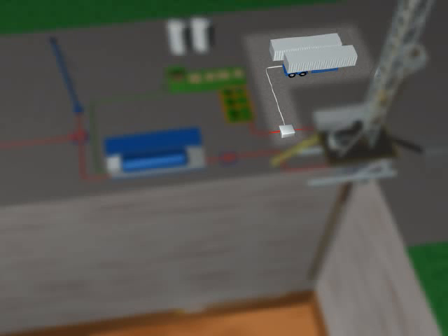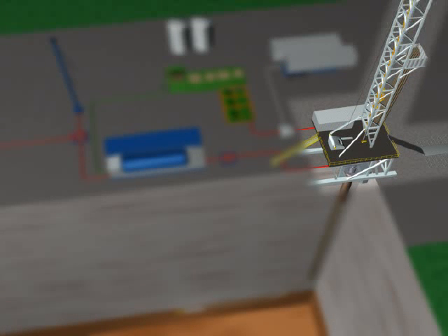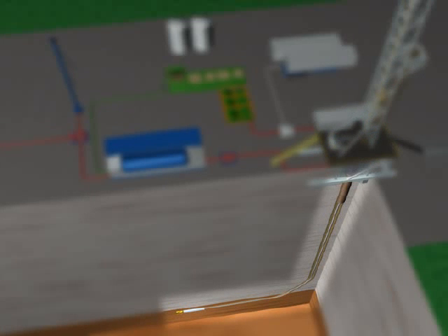Depending on the quantity of nitrogen needed, the source of the gas can be cryogenic tanks or a membrane unit that separates nitrogen from the air. The two-phase fluid stream is injected into the drill string using the conventional rig systems. The two-phase fluid exits the bit at the bottom of the hole, carrying drill cuttings up the annulus.